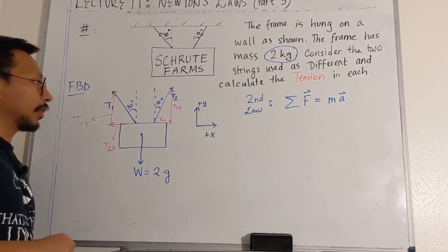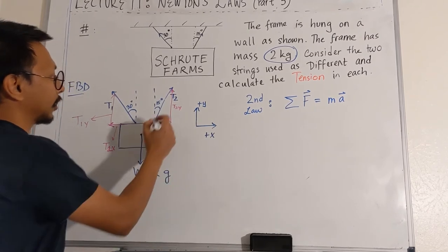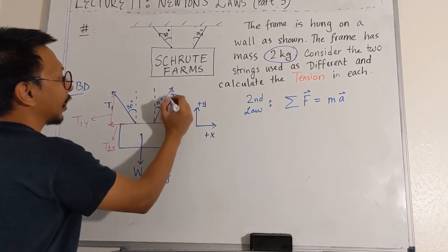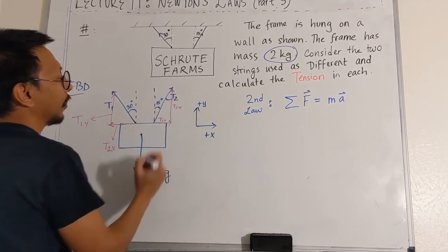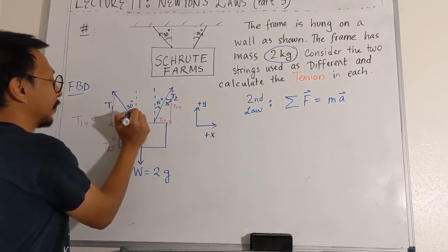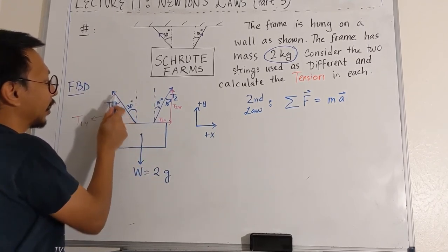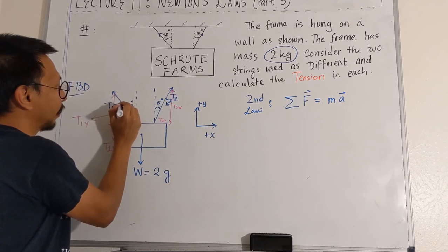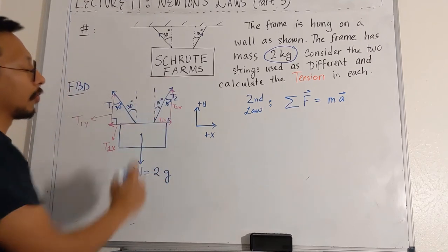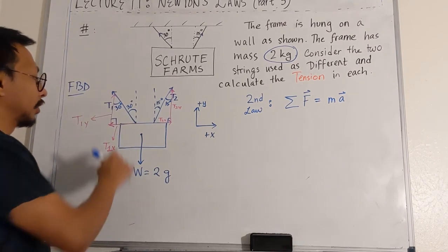The next thing we have to do is find the components. Since this is a triangle and we know this angle with the vertical, that must mean any other angle here, also with the vertical component, would be 15 degrees. Similarly, if this is 30, this is my vertical component and this is the force, so any other angle with this same force on the vertical will also be 30 degrees, and we know that this is 90, this is 90, so that we have a right angle triangle. If this is 15 and this is 30, our job then is to find T1x and T2x.